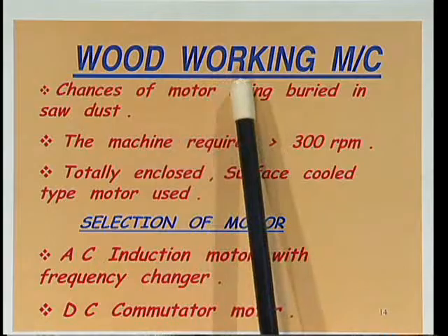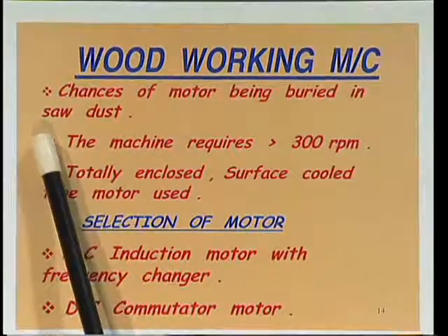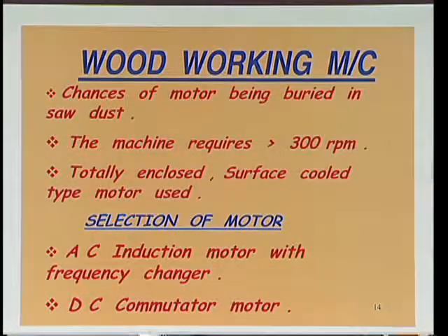wood working machine. Chances of the motor being buried in sawdust. So even this woodworking machine is similar to carpentry work. While doing that work, a lot of sawdust will be produced. So sometimes there is a possibility that the motor may be buried in the sawdust, so that dust can enter the motor and the winding may get destroyed. So we have to remove the sawdust for this type of motor.